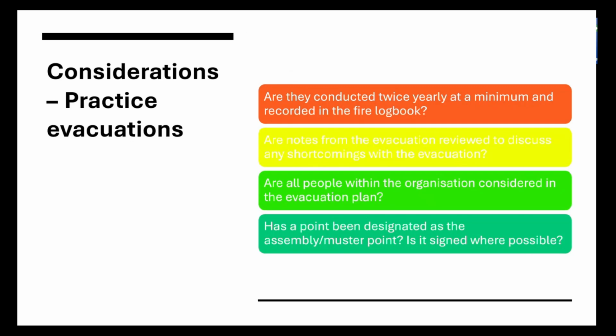Last but not least, practice evacuations. Are they conducted twice yearly at a minimum and recorded in the fire logbook? A note from the evacuation review to discuss any shortcomings with the evacuation. Quite often people will write all these notes in the book and that's it, no more.